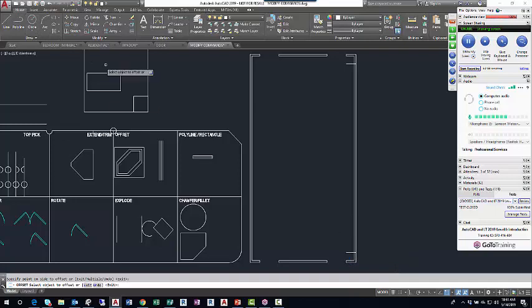And then I'll use the offset again. I'll just restart offset for a distance of 3 feet, enter. Left click the new line I made earlier, move down and left click that other new line I made earlier, move up and left click, and then I'll just cut through these with trim. So trim, enter, selecting the portions of the lines I want to go away.